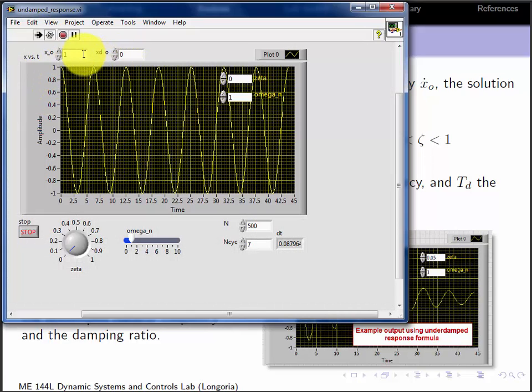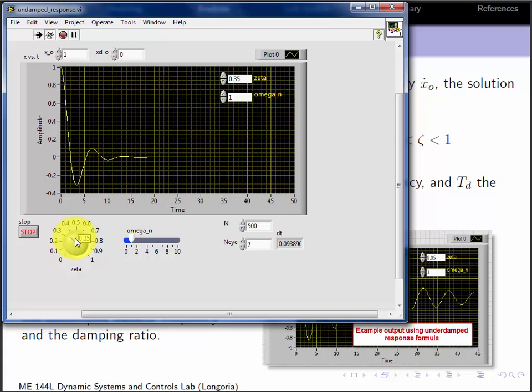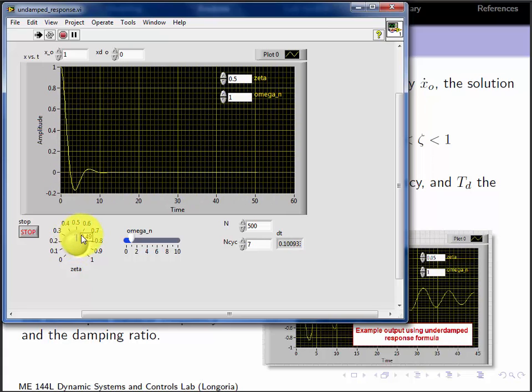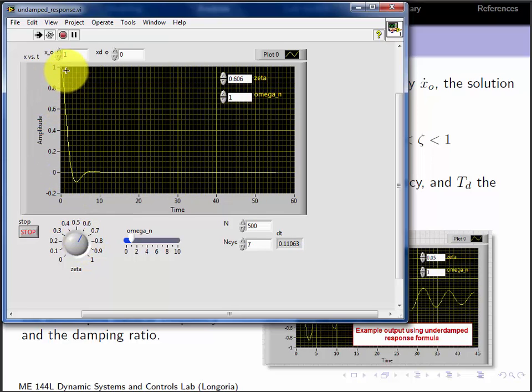So you can see, it's running now with my damping at 0. So zeta is 0. It's indicated here. Natural frequency is 1 for these values I've put in, and I'm specifying those values and specifying zeta. So then you can play with zeta. You can see as I increase the damping, as I get closer to 1, I get very little of what's called overshoot here. I'm releasing it with an initial condition of 1, no initial velocity, and the system's coming back to 0, to the equilibrium.